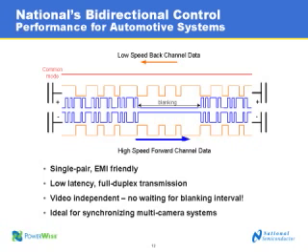The EMI friendly, what this means is you can see the back channel data is switching equal and opposite on both the positive and negative of the differential pair. What this means is we're not doing any changes to the common mode signal of the differential. Low common mode change means no additional emissions.